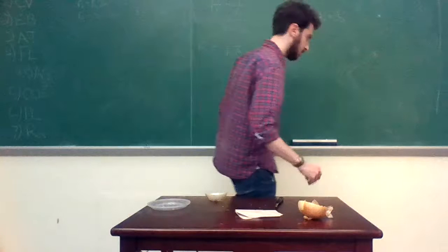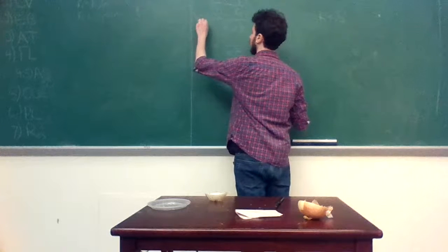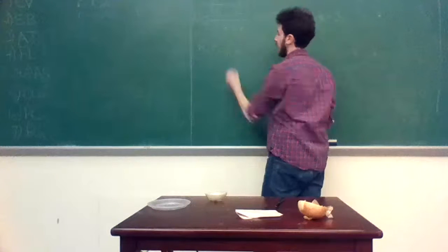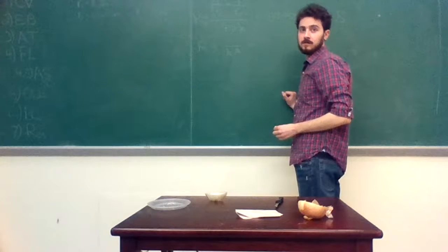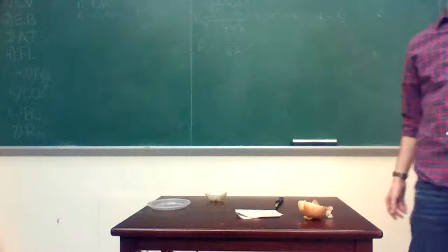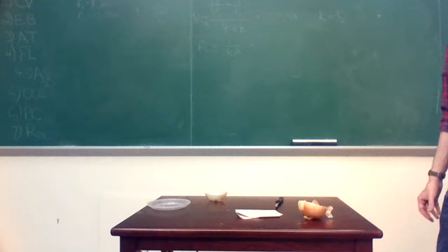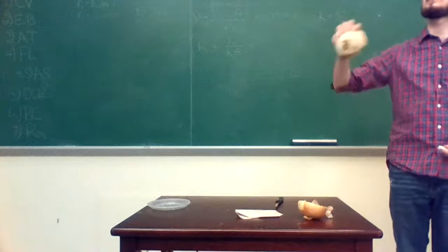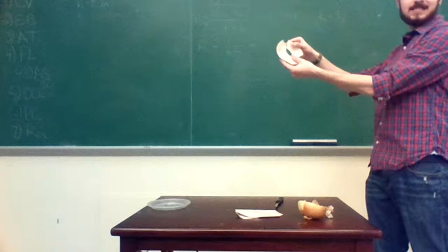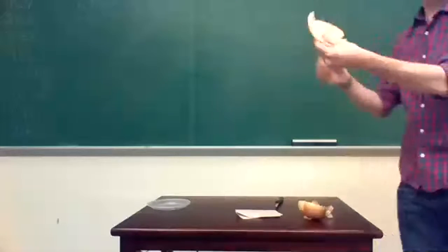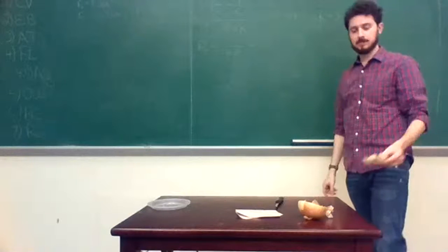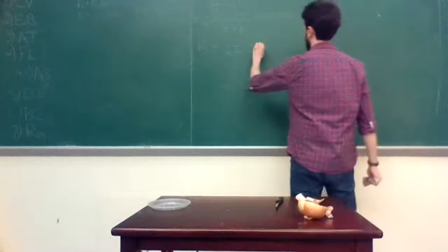Okay, I should have some answers by now. What's the resistance for our sphere? 0.0000159. And L over kA? What is A in this case? 4 pi r squared. Take either one, it won't make a difference. But how does that act as if it's a slab? The idea is, if we flatten this, it's the same area, right? And now we've got the slab with the same area, and you were trying to put the same Q through it. What would be its thermal resistance? 0.0000159. Okay, so the same.